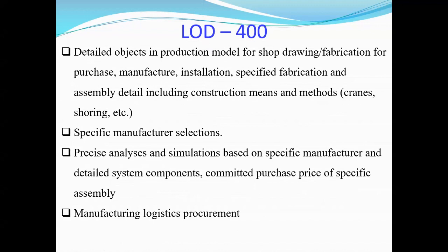As I said earlier, in fabrication I took the example of columns or beams. If you put in the rebar information, such as lapping details and so on, then we are able to produce a bar bending schedule from this beam model. That level of detail can be included in the LOD 300 fabrication level, but not in the 300 series. In the 300 series there is just rebar only. There is no lapping detail, no rebar bend detail and so on. Just bar, that's all.